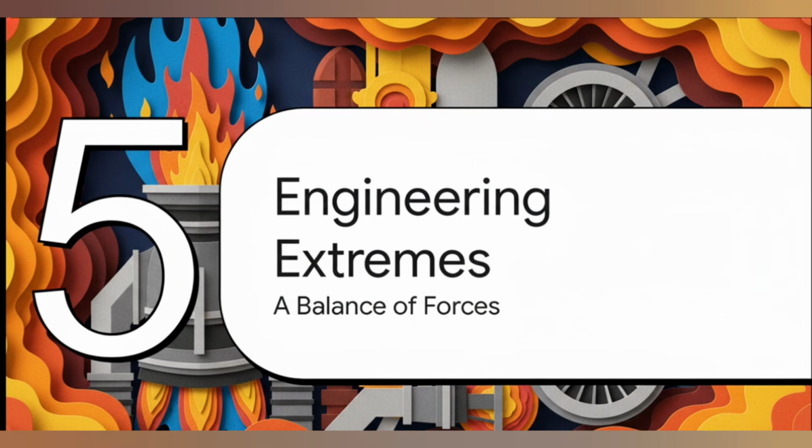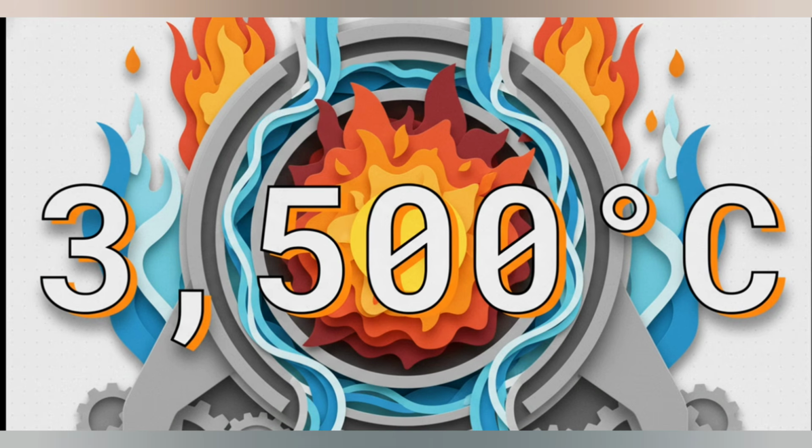Okay, let's wrap this all up by just taking a moment to appreciate the absolutely mind-bending conditions that a modern rocket engine has to not only survive, but actually operate in. First up, temperature. Inside that combustion chamber, it can hit 3,500 degrees Celsius. Let that sink in. That is hotter than the melting point of the very metals the engine is made of. So how does it not just melt? Well, it's thanks to some unbelievably clever engineering where cold propellant is actually run through the walls to cool them down before it gets burned.